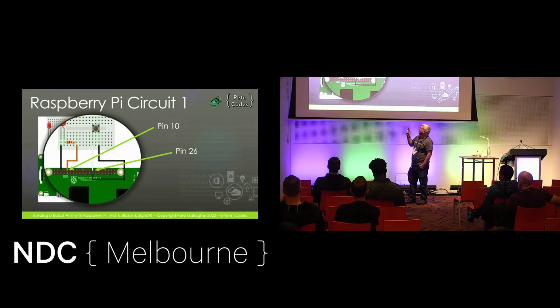Then on here we've got one side of a button connected to the button, and then the other side is connected down to ground. Now there's something missing from this, and maybe the chap who answered about the LED might spot what's missing. Normally what you'd have to have is a resistor pulling that side of the button up to a known value. These are what's called open collector inputs and outputs. So when you set it to be an input, it just floats around.